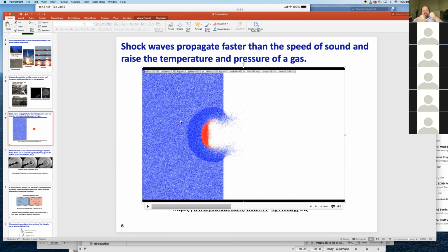And so if you're going to take that mixture, where you can't add any more particles because they're already touching one another, and then you take a 20 GPa shock, what's basically going to happen is that the particles themselves are compressible, and so the Baer-Nunziato model is designed for that really highly packed, very high pressure condition, and it's really specialized for that type of condition.